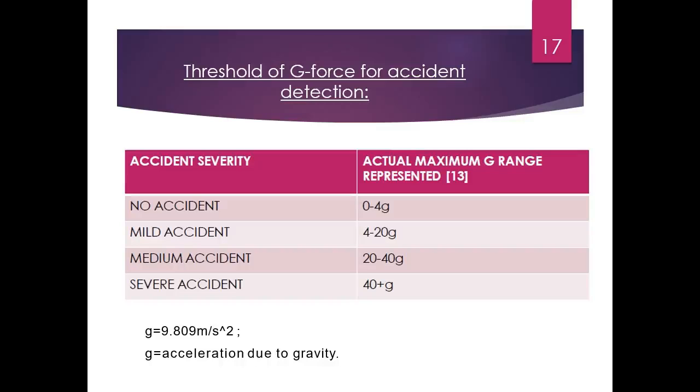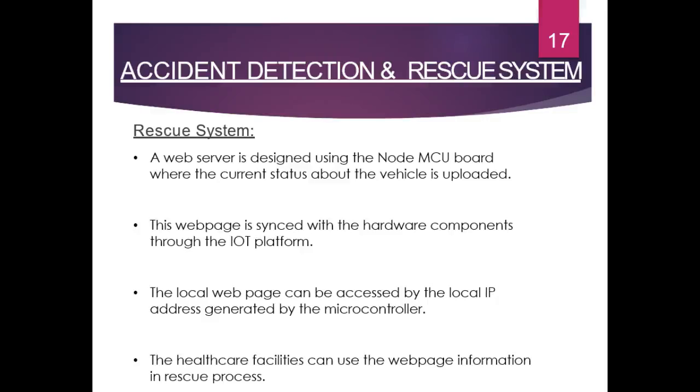So after detecting the accident, our next motive is to rescue the victim. In the rescue part, the information of the victim and his car is sent to a web page. The web page is designed in HTML. The use of the NodeMCU microcontroller enables us to synchronize the HTML-created web page along with the hardware components. The web page can be accessed with the local IP address that is generated by the microcontroller. The healthcare facilities can use the web page information in the rescue process.